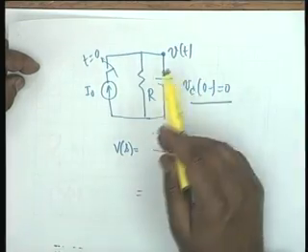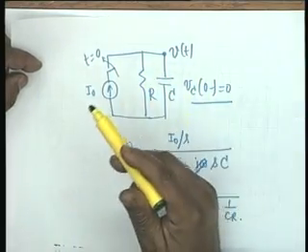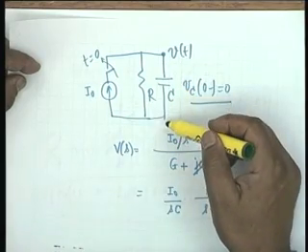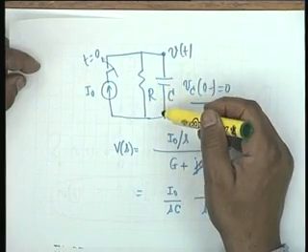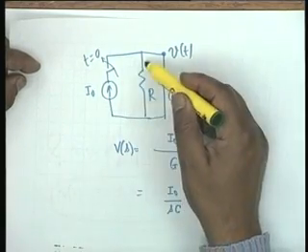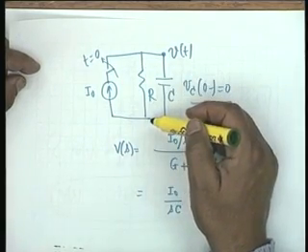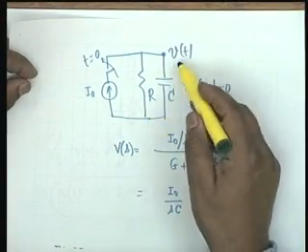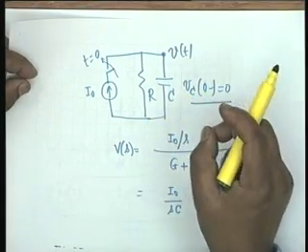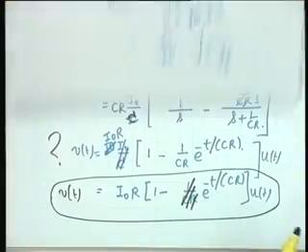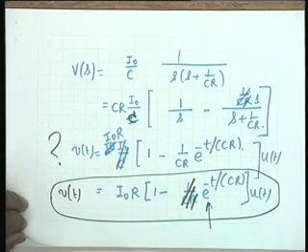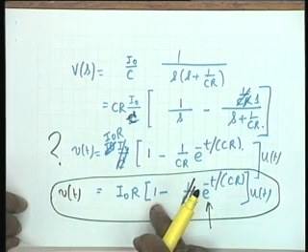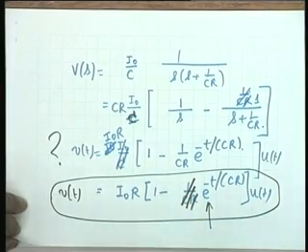This stands to reason. Now, if this current stays for a long time, then the capacitor will be fully charged and will not allow a current to pass through it. So the total current I0 shall pass through R, and therefore at infinity V(infinity) should be simply equal to I0 multiplied by R. Now, is this borne out by mathematics? Yes. This term goes to 0 as t tends to infinity, and therefore V(infinity) would be simply equal to I0 R. So the result is correct.